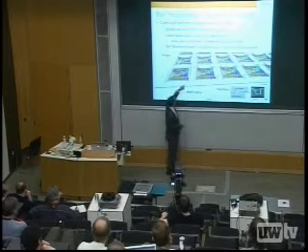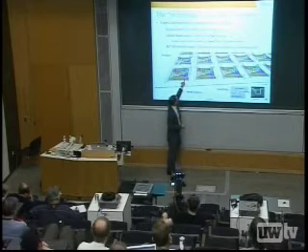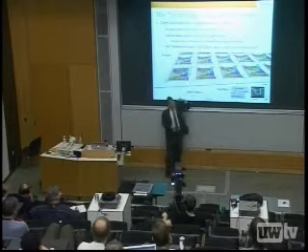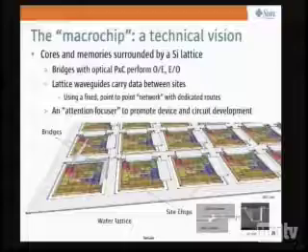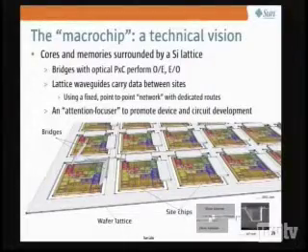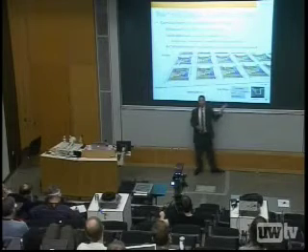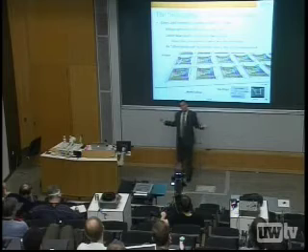So the idea is we have circuits on this island chip that can communicate to this bridge chip, perhaps through fine-pitch solder, perhaps through proximity communication. And that data then becomes optical on this bridge chip, runs into a waveguide on the bridge chip, and the waveguide talks to this lattice and just transmits light back and forth. All right? If you can do this, then we can talk about transmitting data from one lattice point to another lattice point, another island, using purely optical communication and therefore the speed of light.